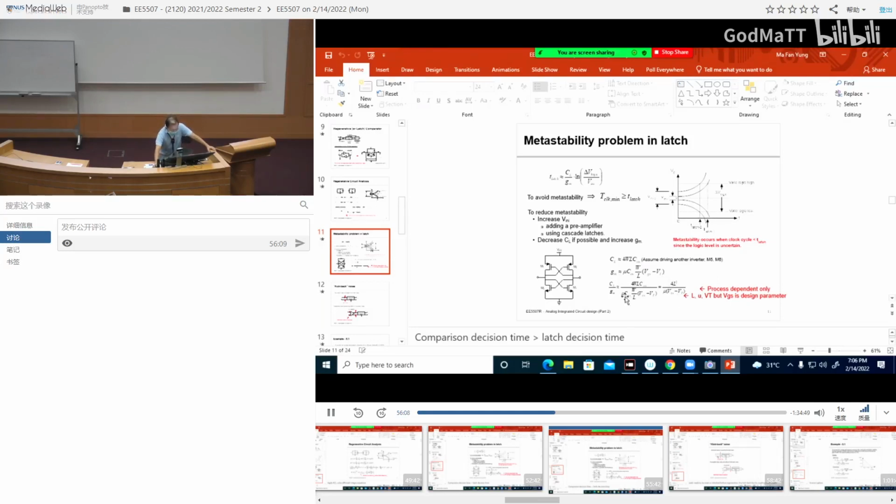Okay, so to make CL over GM as small as possible, which means to lower the settling time or to increase the speed, if L can be smaller, I will get a speed increase. L can always be smaller because with each technology generation, L is smaller. TSMC is now at 4 nanometer, or 5 nanometer, or 7 nanometers production. The next generation will be 4 nanometers or whatever. So with each technology generation, L is getting smaller. That's why automatically the circuit is getting faster. You see?